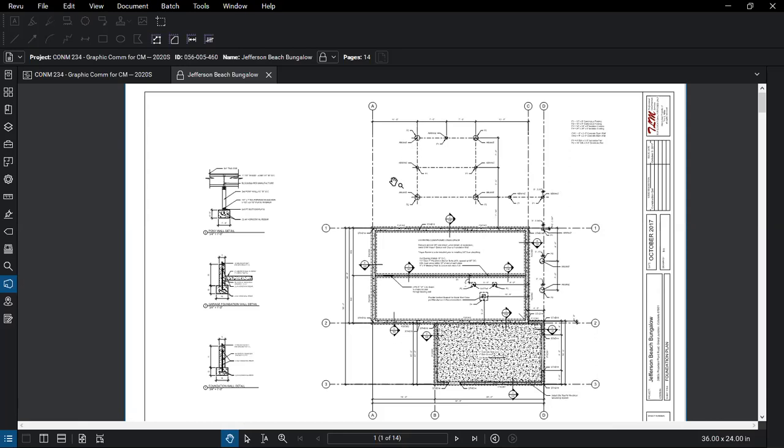When we start looking at the grid line, it's kind of like that standard convention with the main level floor elevation of being 100 foot 0 inches. What we want to do is take the intersection of two grid lines and make that our relative absolute point, if that makes sense. It's relative in the sense that a building can go wherever it wants in a coordinate system.